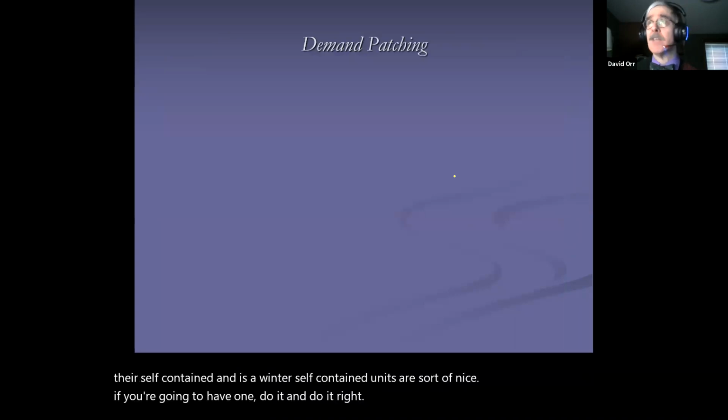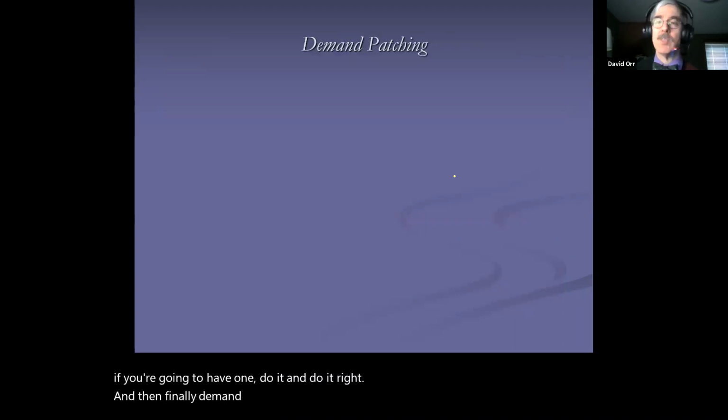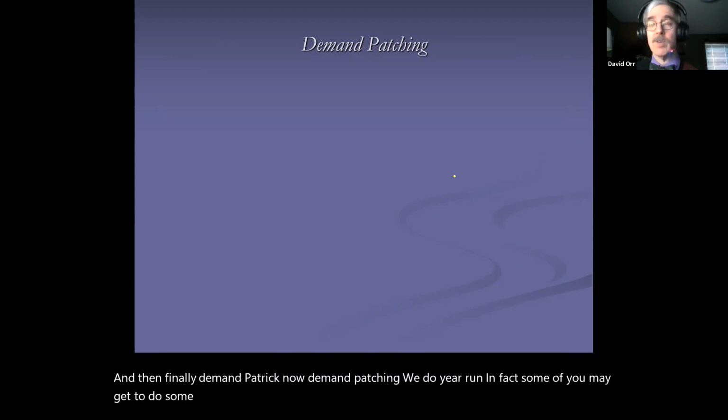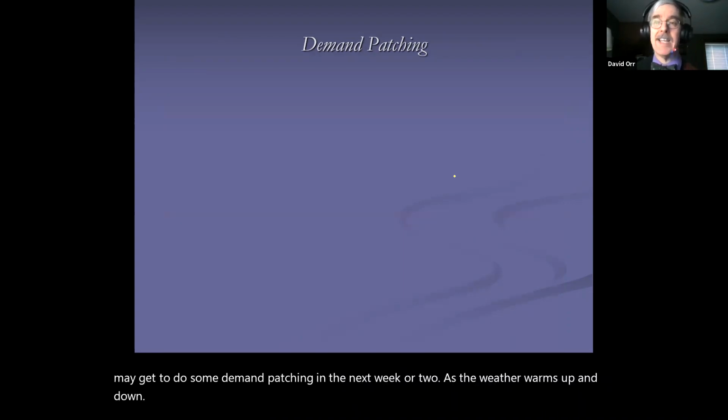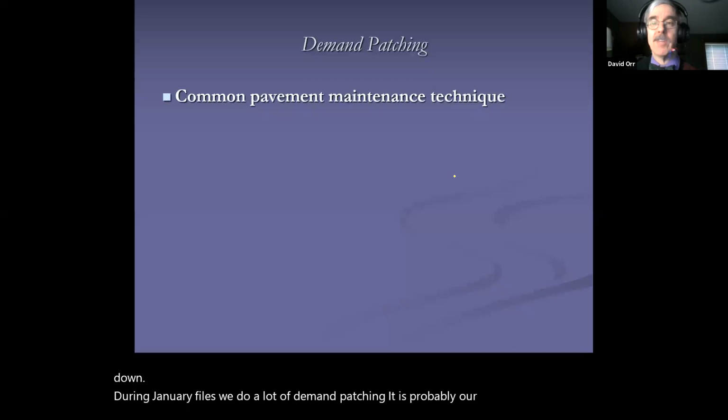And then finally, demand patching. Now, demand patching we do year round. In fact, some of you may get to do some demand patching in the next week or two as the weather warms up and down. During January thaws, we do a lot of demand patching. It is probably our most common pavement maintenance technique.